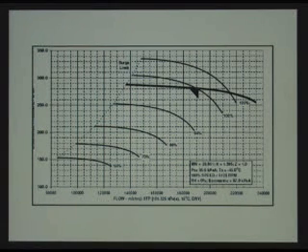With this lower rise and almost linear section here, this would be a little more difficult to control accurately. Depending on the process, if the process doesn't change very far from this operating point, this may be an acceptable performance curve. If you wish to operate all the way from surge out to your high flow range, and your process will be at the high flow more than the low flow, you may want this because you can get more flow with this compressor.